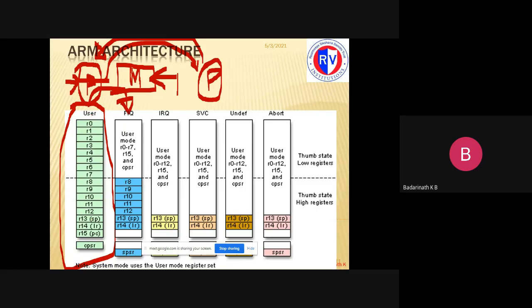Always, when you get an interrupt, how fast you can switch to the program and start executing, that we call latency. The lower the latency, the better. The more time you take, the more data you are losing from the sensor.